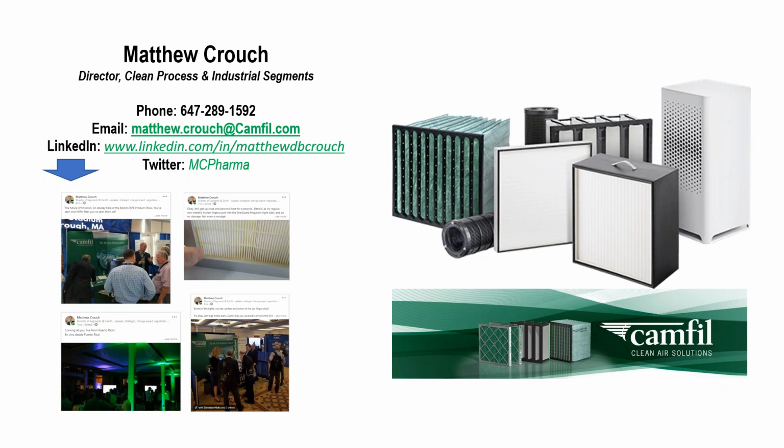The only other caveat to that, Kevin, is the airflow and pressure drop ratings. Because the EnerGuard runs at a lower pressure drop than glass, you want to make sure that you're balancing the airflow to the space to accommodate for that lower pressure drop. So whether that's a constant fan or, hopefully if it's a sustainable facility, wink, wink, it should be VFDs. So they'll automatically scale back in order to accommodate that lower pressure drop. But if it's an older facility that's still running on a constant fan, you're going to have to be cognizant of the airflow. Fair enough, thanks.